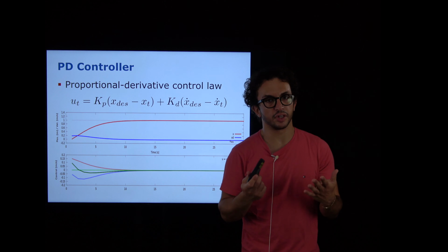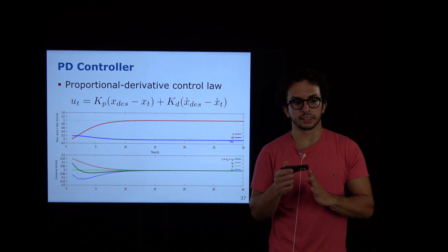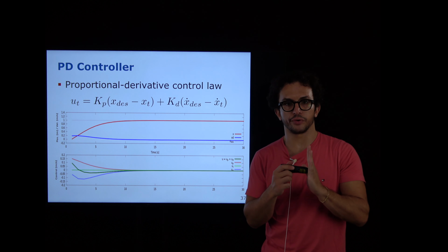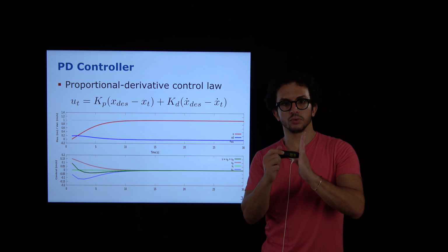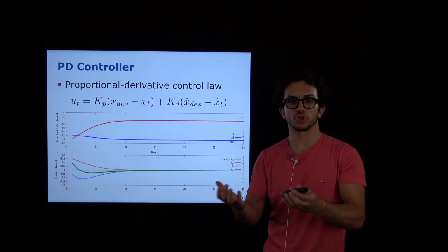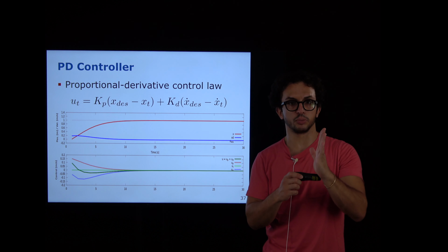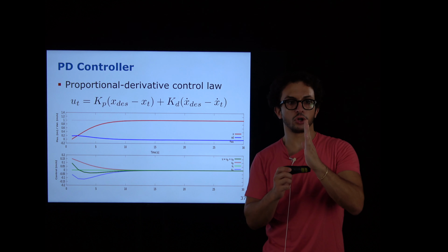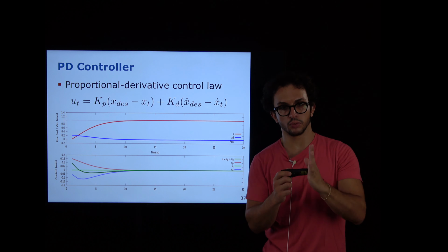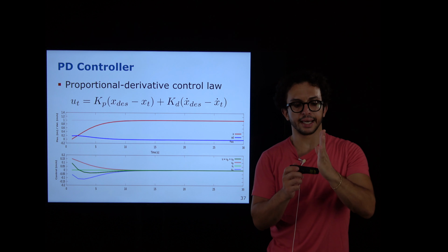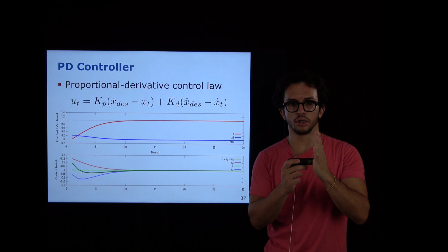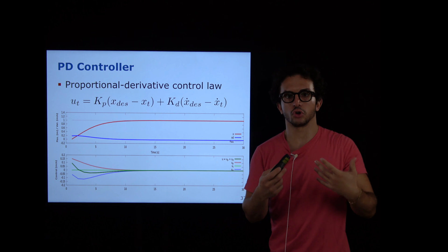Since it was not aware of the velocity, what was happening is that when the error hit zero, in the instant the system was passing through zero error, it still had a velocity because that was not controlled. And so the system kept moving. At some point it stopped, because it detected the error going in the opposite direction with the opposite velocity, so velocity with opposite sign. And again, when the error was at 0, the velocity was still not 0, because the control system was not